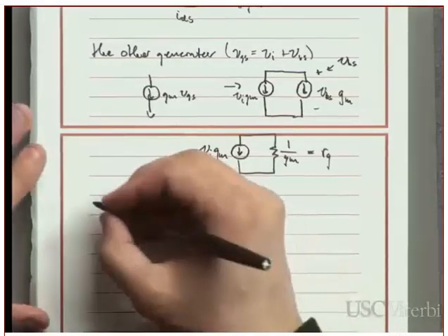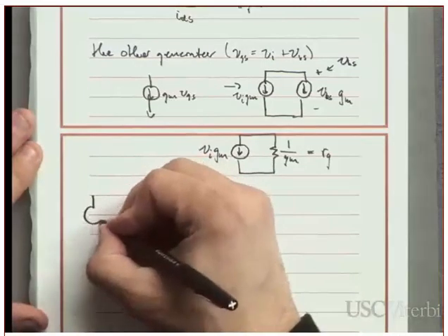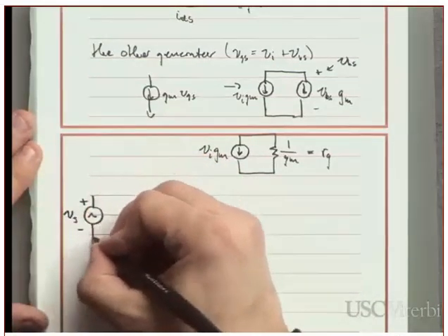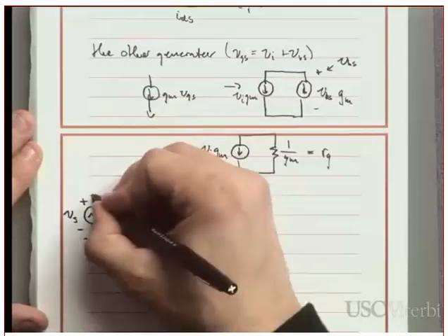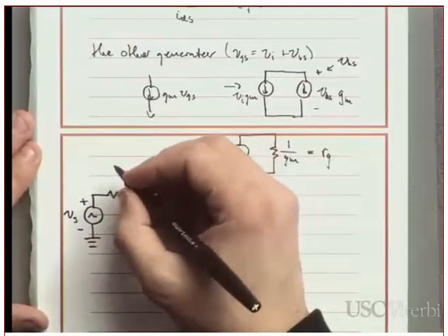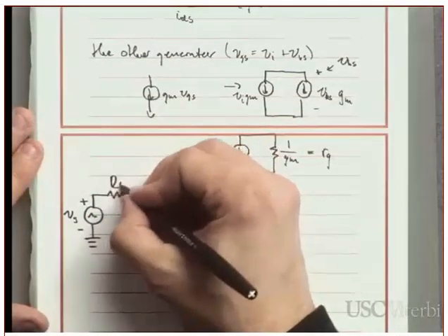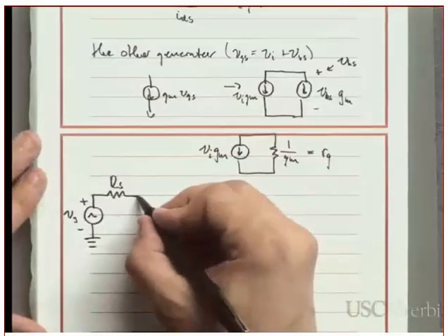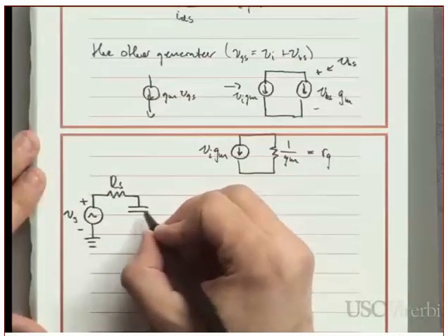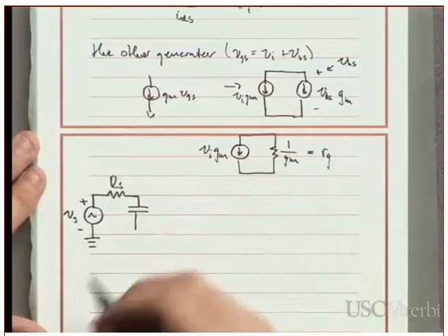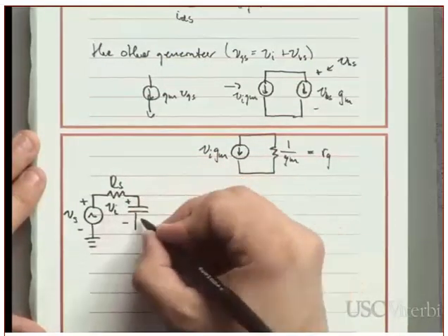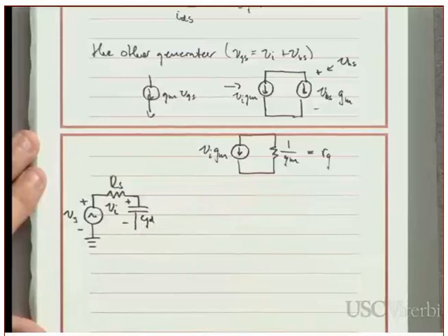Okay. And when you do this, you actually end up switching the direction of a lot of things. So I'll try to note all of those when I do that. So there's RS. All that stuff's the same. Now, here's where things start to look a little fishy. I'm going to put VI here, which means that this capacitor is the gate to drain capacitor.